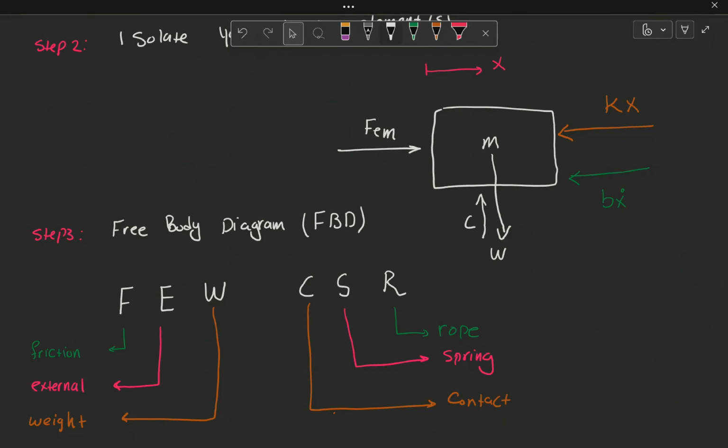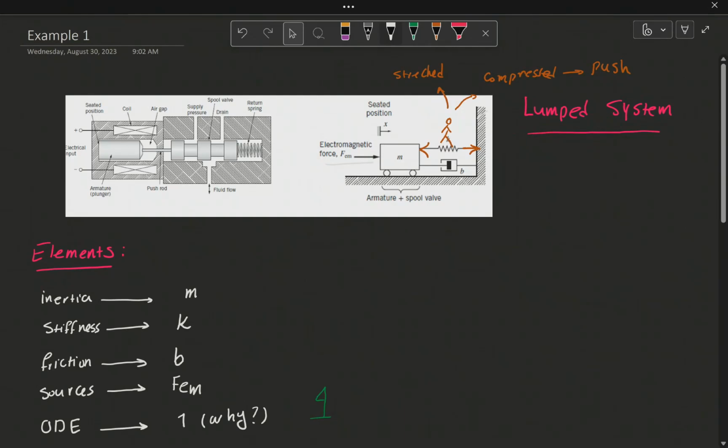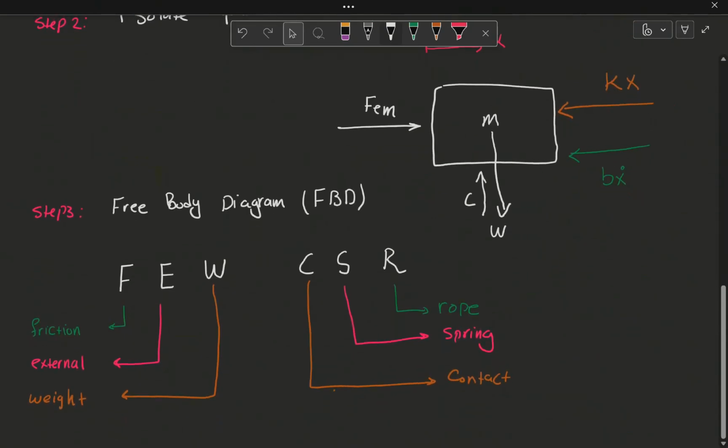As an engineer, you are expected to draw flawless free body diagrams. This is one thing that people are asking you to do. The other thing is, look at this free body diagram and the motion of the box. If you look at this, you see that the box has no upright motion. There is no vertical motion in this direction. The only motion that we have is a horizontal motion, which means that the vertical motion is actually a static motion. There is no acceleration. And since there is no acceleration, it's very boring and very simple.